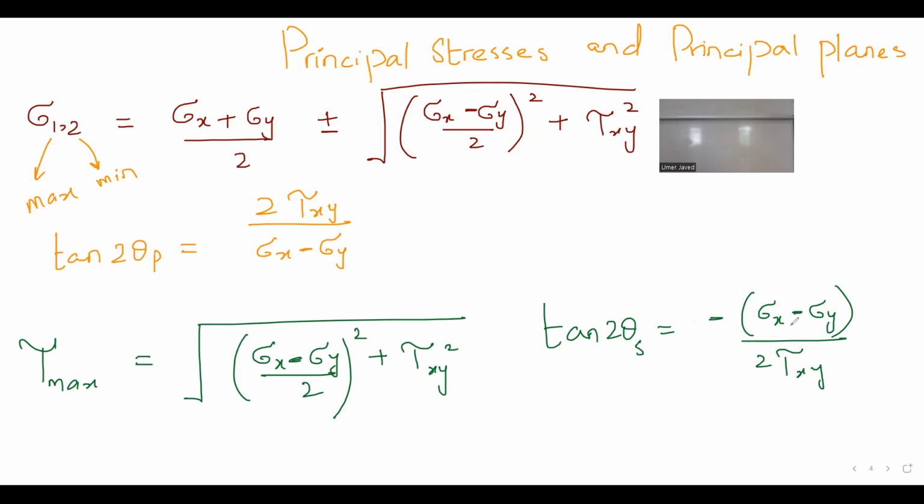If we have a wooden stick and we keep pulling it, it actually breaks between 42 to 45 degree angle, because of course that is not a 100% homogeneous material, it has fibers. So technically that 42 to 43 degree that you are getting is because of this, that when it breaks at 45 degree, it breaks on a maximum shear plane.